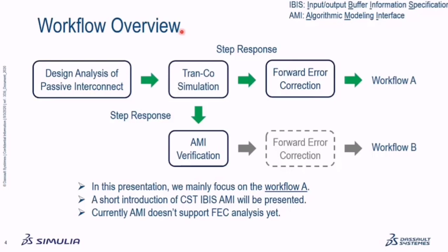Currently, AMI cannot handle FEC for the error correction analysis, and it cannot model the error propagation effect. So you have to do some programming and signal processing work in MATLAB or in Python, or I did it in the VBA integrated on the CST platform, which is quite nice, and we can have a look later together. So we don't use AMI simulation in this case, but you can use it, and we do the equalization and the random jitter with the CST eye diagram tool. We will look into the details later.